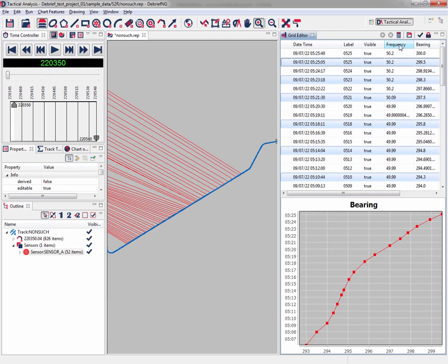And as we saw before, the sensor data was ambiguous. And this can happen when the data has been produced by a towed array. In this current scenario, Debrief is plotting the sensor cuts against the attack datum of the platform, but we need to apply an offset of 451 meters in this particular example for this sensor. And this is minus 451 because it's towed behind the vessel.